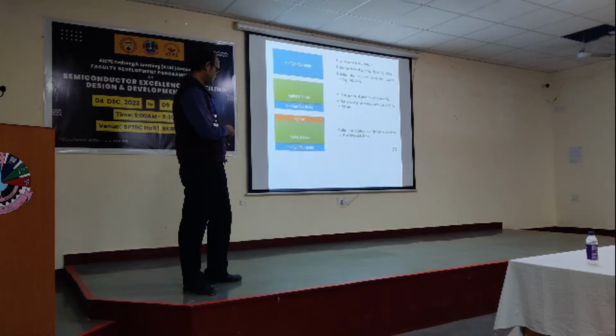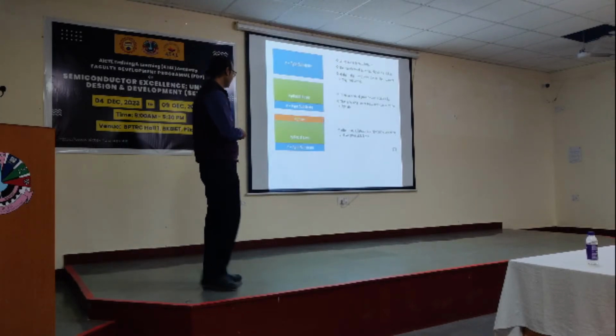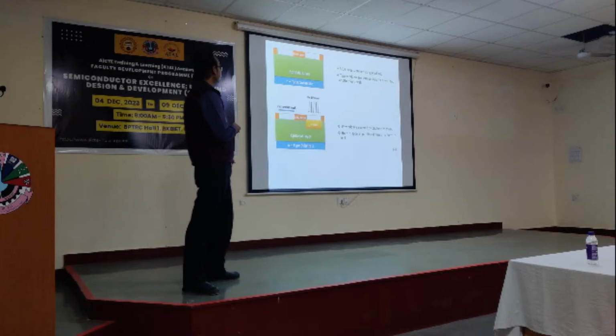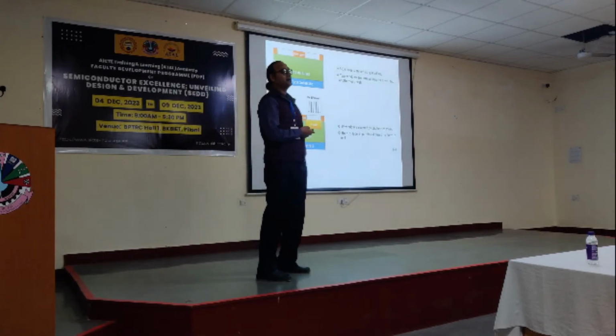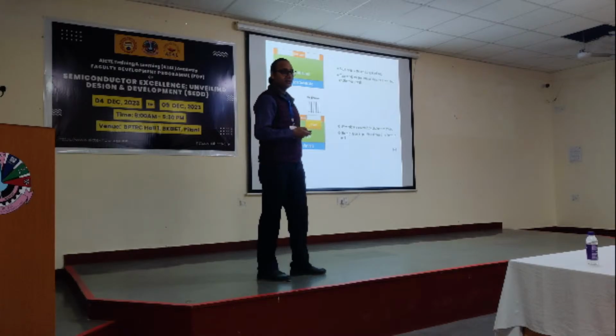So we have discussed up to this point. Then what will we do? Where were we? The SiO2 layer. Then we will etch that SiO2 layer at this point and at this point. Why? Because I will have to implant the N-well and P-well now.